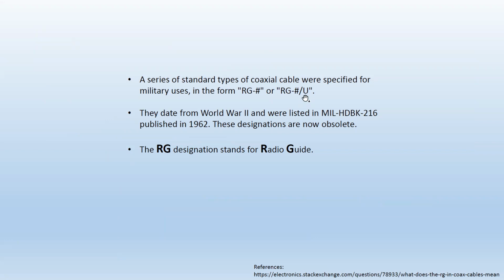If you install a cable that is not UV rated outside and leave it exposed to the sun, within a year or so, you can grab it by your hand, squeeze it, and the whole jacket is going to turn into dust. Right? That's how strong the sun rays are.